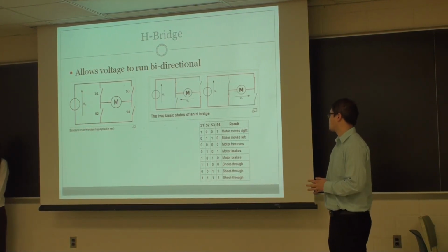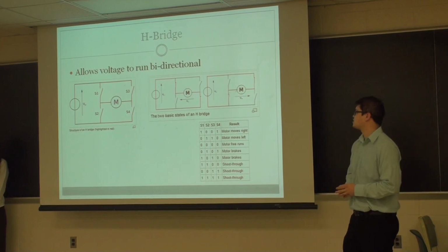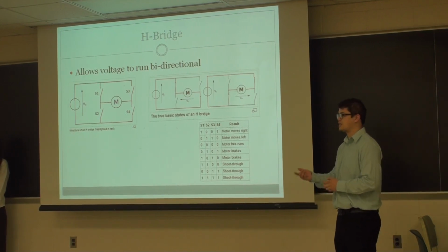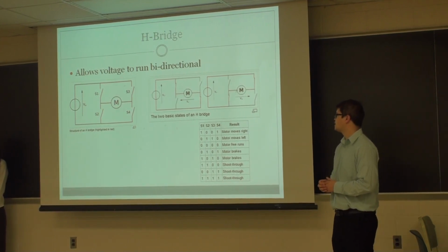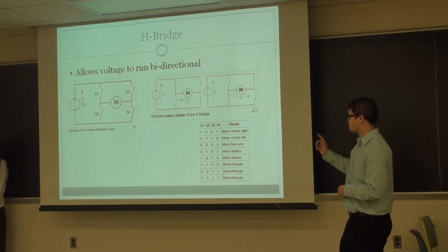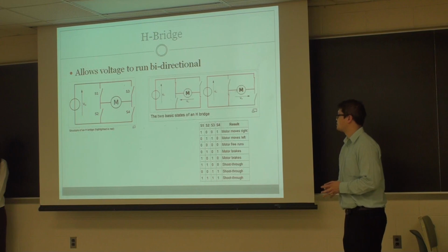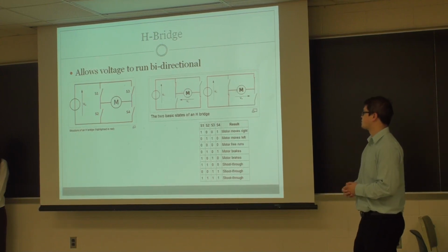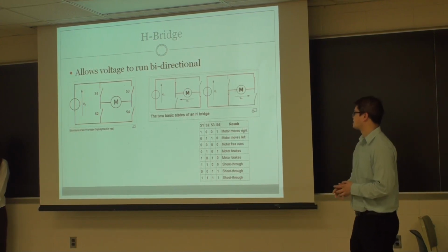Besides that, you can also do other things. You can brake the motor. Normally it runs at 0, 0, 0, but when you want to brake it, you're going to want to close S1, S2, or S3, S4. And those are some of the main states, but for the most part, you just use the two basic ones, moving right and left.